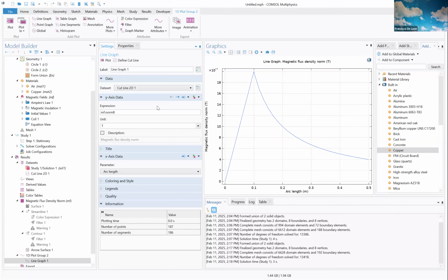Why is the rise linear and the increase very steep, but the drop is not? It all depends on how you're integrating this. You start with 0, the current is 0, so the field is 0. You integrate a little bit. Say this is your conductor. Here, nothing. Here, you have this current. Here, you have that current. Over here, you have the total current. And then once you get there, it goes out because it's not enclosing any more current.